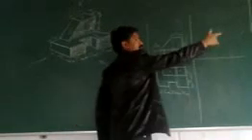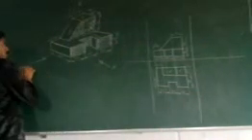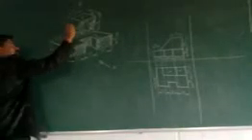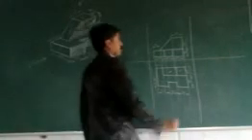Now concentrate on the side. Please observe from this direction. In this direction, this rectangle is visible, and this slope rectangle is also visible, and this groove is not visible from the left side. Why? Because this area covers this groove, so this groove is not visible. So here we indicate the dotted line in the side. See here. Simply project this line.